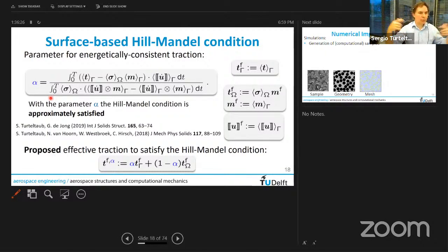And so we really automate not just the post-processing, but the whole process from a database to creating a sample, putting in the properties, creating the mesh, putting in the cohesive elements, running the simulation, and doing the post-processing. All of that was fully automatic. So we took the person away, so we could run this every evening. It's computationally expensive, but if you have a nice script like this one, just click on that and let it run every evening. And we didn't even notice that being a big issue.